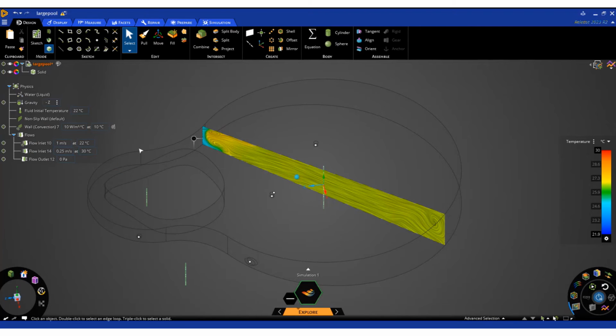Discovery simulations provide you a very good understanding of the flow physics that is going on. But if you want to run more detailed analysis, say, for example, species transport, reactions inside the system, sedimentation, etc., you will eventually have to move this model into Ansys Fluent or CFX to run these kinds of multi-phase models.